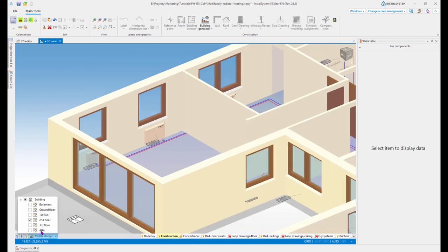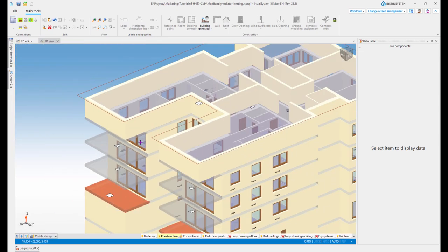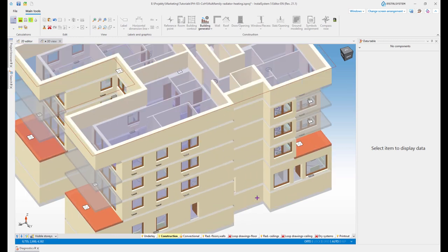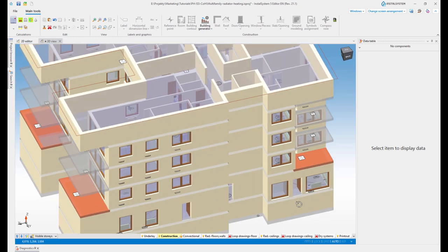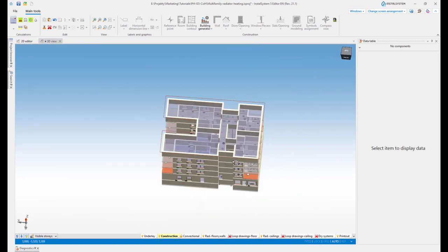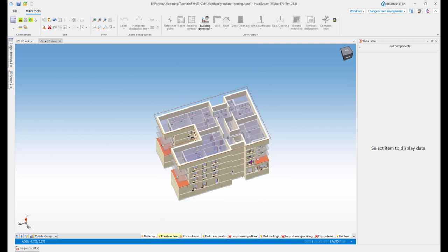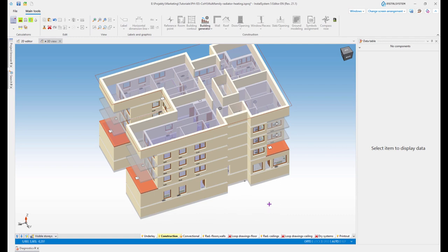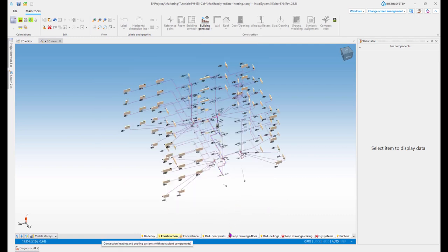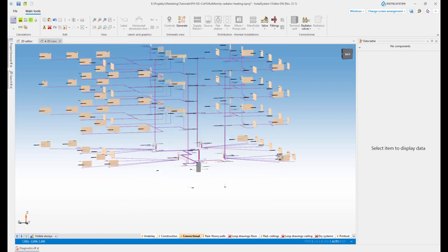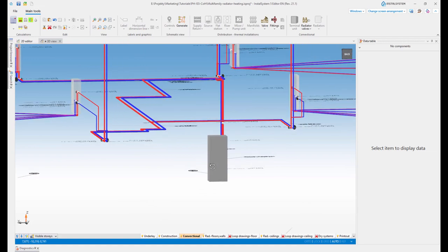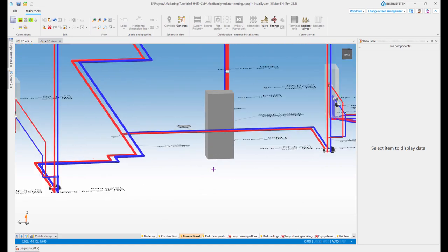So let's imagine that this is a standard situation: the walls are insulated, the roof is insulated, and the installation is partly replaced. Because of additional insulation of the wall, the heat demand goes down, so it's reduced. And usually in scope of installation, the part of installation in the basement is replaced with new pipes and new balancing valves and new insulation.